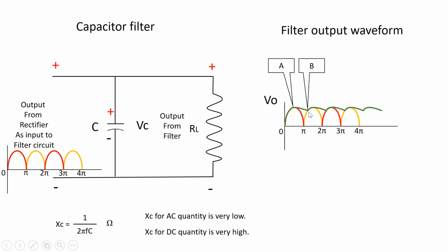With this supply of the load current by the rectifier diode, the capacitor again charges to the next peak, and the same sequence of operation will be repeating in the subsequent cycles of the input. Due to this improved waveform of the capacitor filter, the ripples are reduced to the lower value, from the point A up to this point B differences only.